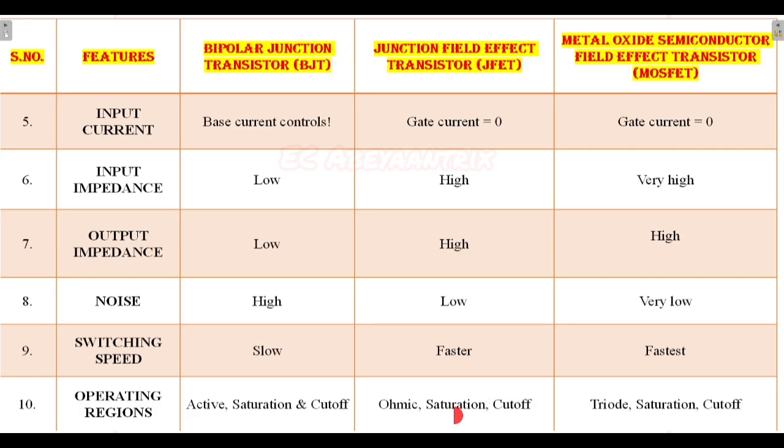And in JFET, we have also learnt about pinch off voltage. You remember that concept? Pinch off voltage is the value of the reverse bias voltage at which the depletion region completely depletes the channel width and nearly touches the two regions, so the channel width is nearly zero, and as a result, the drain current becomes zero.